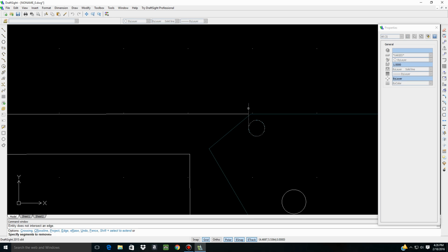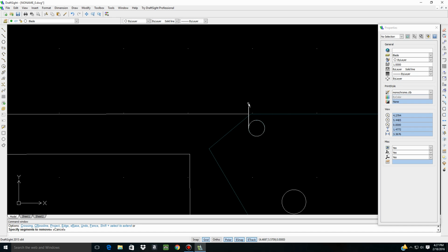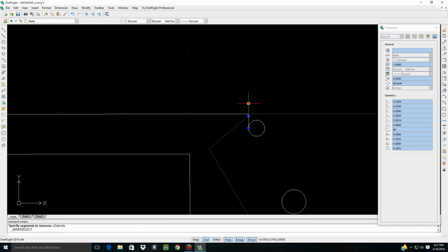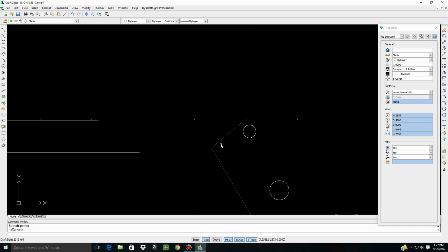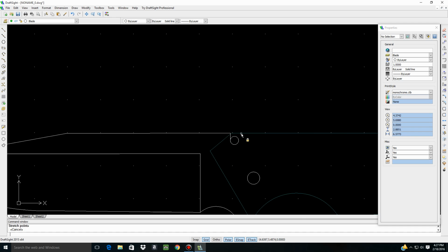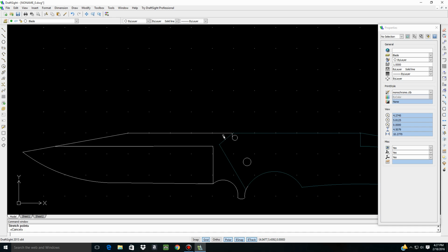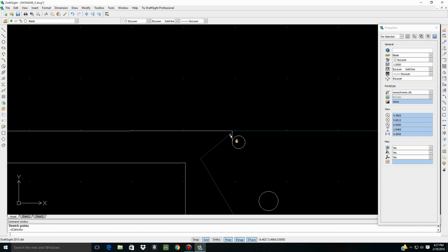Oh no, it's not going to let me trim. It won't let me trim because there's no reference point on this side. So that's okay. We could just take it and shorten it. So highlight it, grab the end, and bring it to the end point. Boom, just like that. See, now our blade will stop against that pin in the open position. That's great. That's what we want.